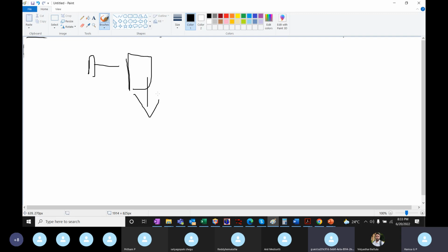There a LIN protocol will be used. It requires your input, where you are giving the input and it will be considered, and LIN protocol requires an input from the master. Here you are the master, who has provided the request, and a LIN protocol is used in that type of power windows and power doors, because even if it is not working, it is not going to affect your life, correct? So it is used in less critical functionality, not in high critical functionality. We will come back later to what is less critical and more critical and why exactly LIN.